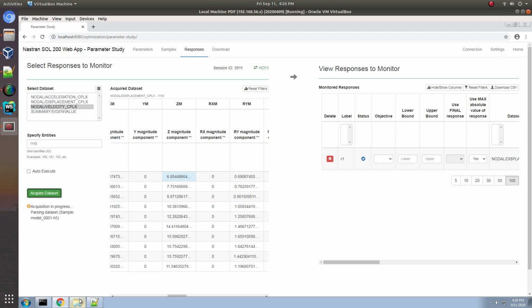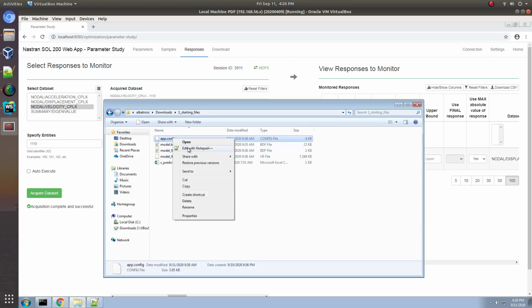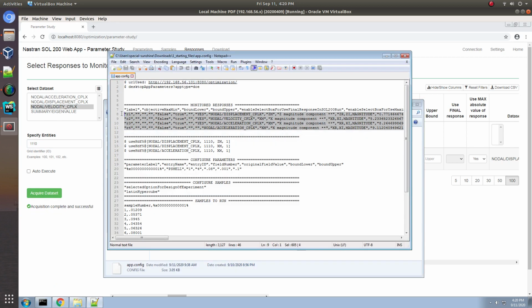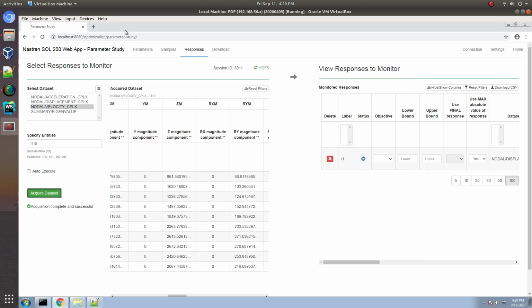Now, why am I doing this to begin with? Right now, the old parameter study files are only tracking 4 responses. But if we want to perform a regression for the entire XY plot, we have to track every point of the XY plot. So that's what we're setting up right now. Actually, I can show you right now.